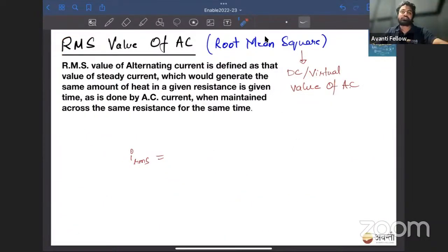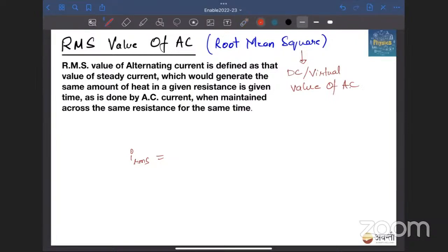How to find root mean square: for finding root mean square, we have to go back, start from square. Look here carefully. First, square the current. We have done square, very nice. Now we will take mean. For mean, the total current flown in time 0 to t.